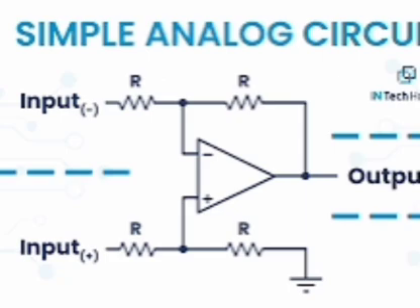Special multi-stage amplifiers. First one, Darlington amplifier; second one, Cascode amplifier. Darlington amplifier is a cascade of two common collector amplifiers or a cascade of two common drain amplifiers. It has unity voltage gain, very high input impedance, low output resistance and high current gain. It is used as a buffer.